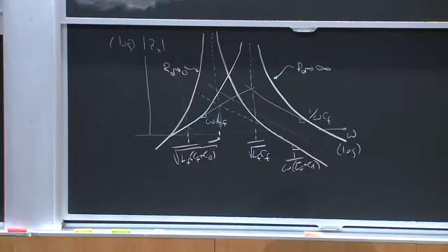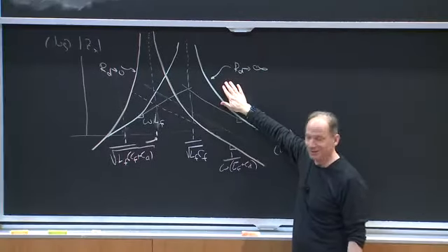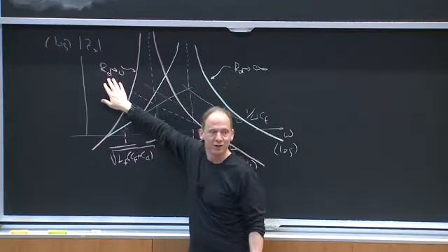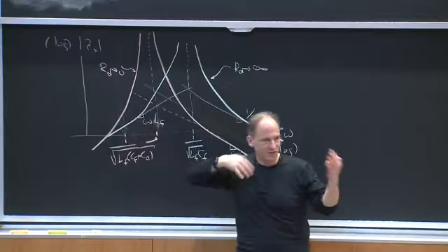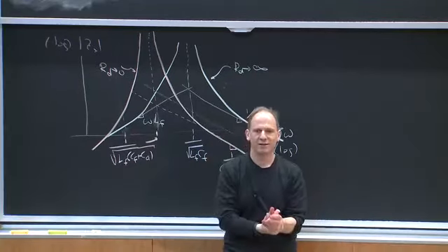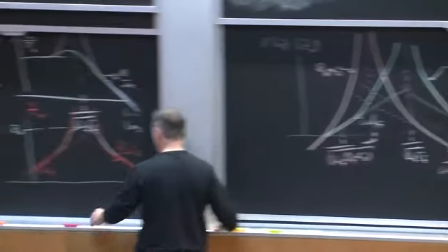So this is sort of a Goldilocks thing. If you make your damping resistor too big, you get bad damping. If you make your damping resistor too small, you get terrible damping. For a given value of CD, you've got to pick the right damping resistance. What would my output impedance look like if I picked the right one?